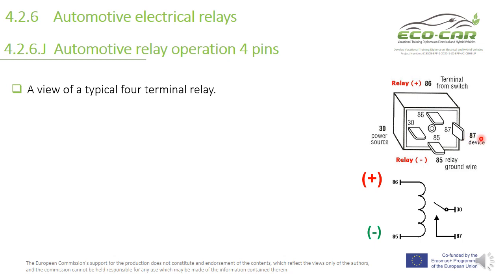or, as also, you can connect it in another circuit to control this device or the load. If you apply here a voltage, depending on the relay, for example 12 volt DC, this coil is energized, and this armature of the 30 pin will close to 87. So we can test whether this relay is okay or not by applying the voltage here.